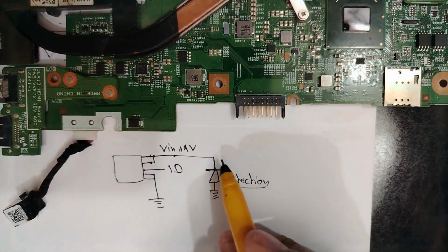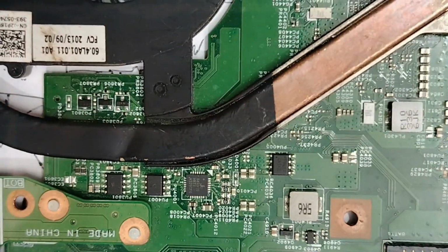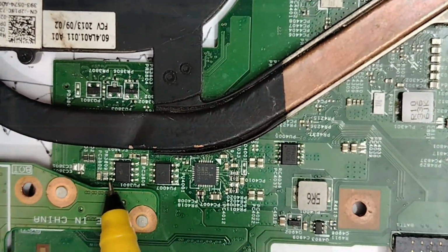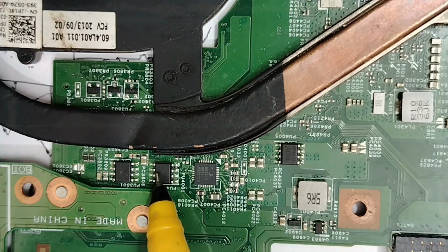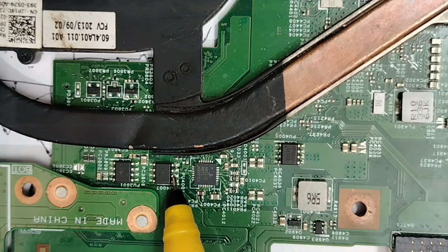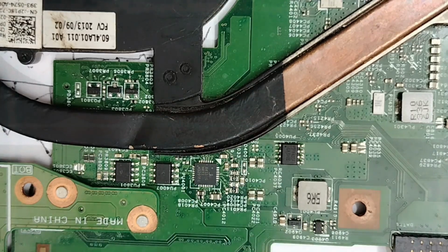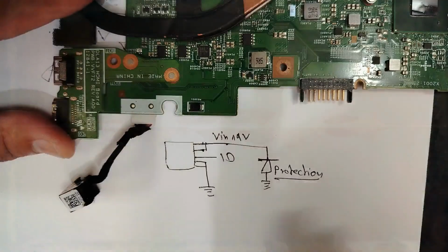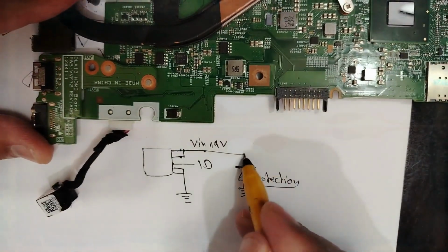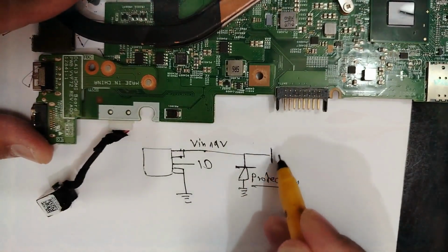So let's zoom in a little bit to know exactly. Here for this one we have the source. This is the source here, and we have the drain connected to the drain of the second switch, and then the source of the second switch is connected to the current sense resistor. So let's zoom out again, guys. So we have the first switch here.